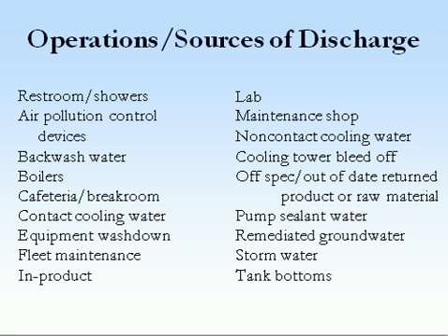I have been to an industry that's a food producer that was having silver violations. That didn't seem to make sense, that a silver violation would be coming from a food producer, but it turned out that the silver was coming from a test that was being run in the QA/QC lab. So you want to make sure that you're aware of what's happening in those labs.